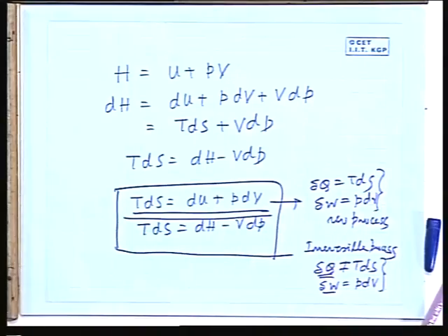Because in an irreversible process, the work transferred because of the displacement is more than the PdV. That means if you equate PdV work for a piston displacement, in an actual case if you displace the piston in a finite time and measure the work done by any dynamometer, you will see that delta W is more than PdV. Okay? That's fine? Okay then.